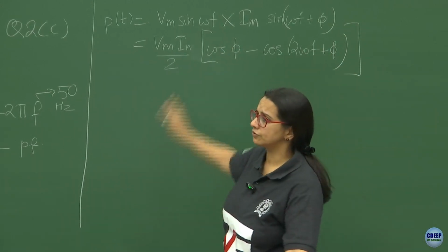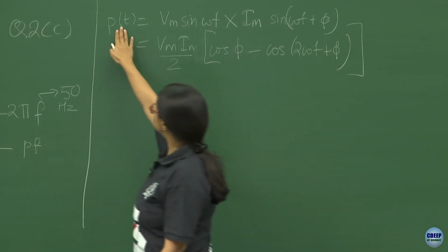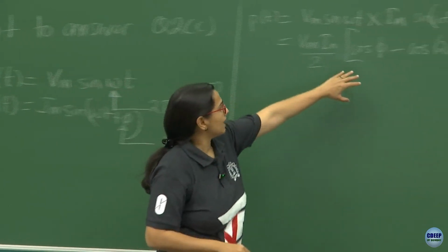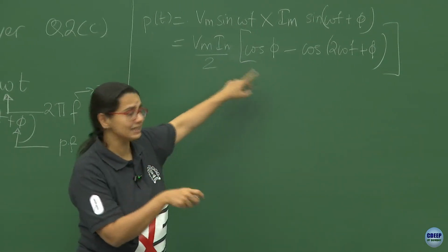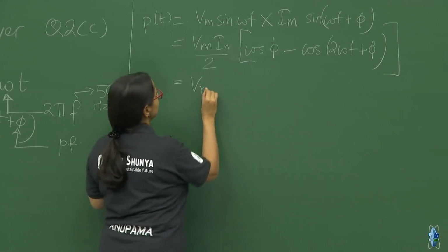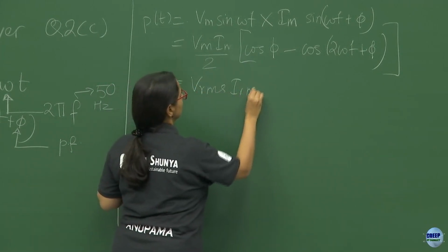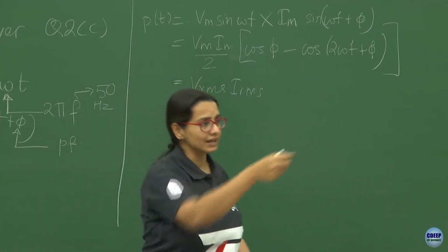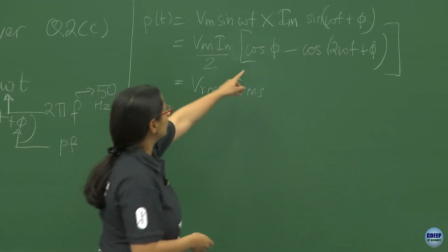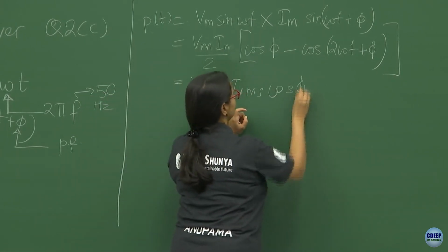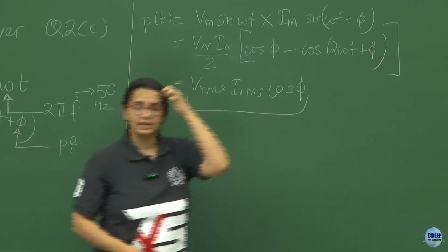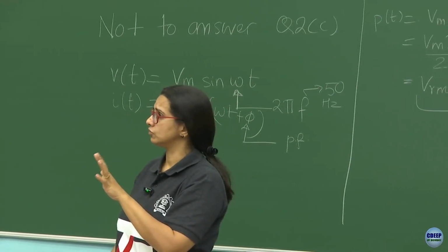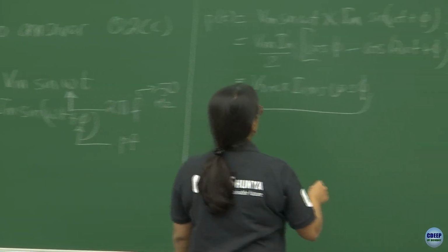This is fine. So far so good, right? Your instantaneous power has some average value, and this you can instantly recognize. I could write it as V_RMS, I_RMS product now, because this 2 root 2 I can just distribute, correct? And that means I get my V_RMS, I_RMS, into cos phi. This is exactly what you recognize as active power, correct? So far so good.